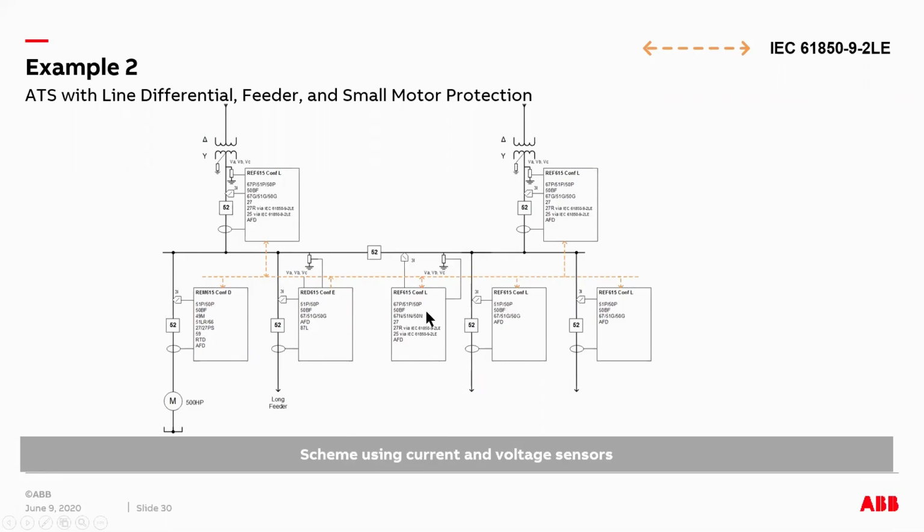As you can see here, even though it's the same relay, configuration L, we can use different protection functions for this one because it requires additional functions as a tiebreaker, whereas the feeder relay may not require all the functions used in the tiebreaker. So we can disable those or delete them altogether. There is a great amount of flexibility in how things can be tied together and programmed in the relays.